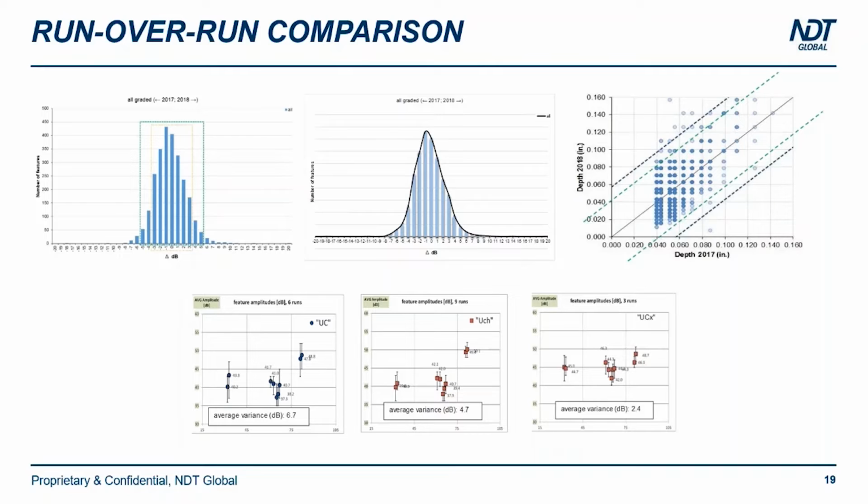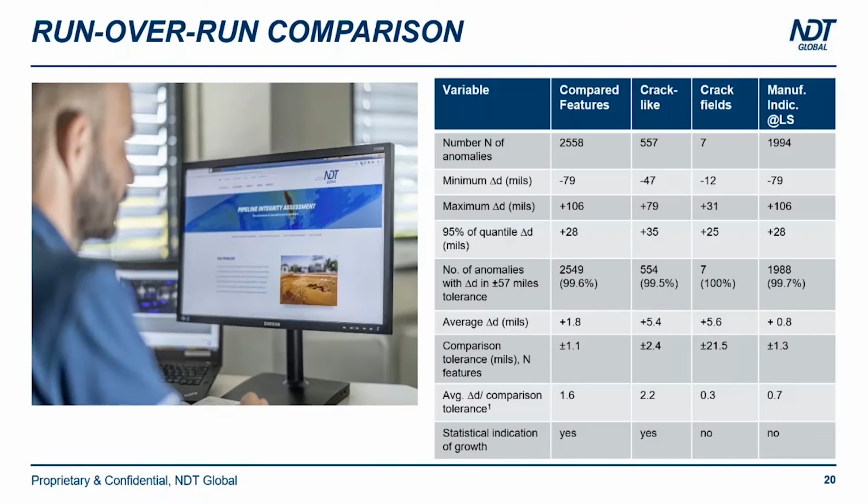So this is extremely important. This is something that is being done from the beginning for every inspection that we have. All these outliers, variances are communicated and explained to the operator beforehand, but we can also create comprehensive studies out of it. These comprehensive studies could be translated into a crack growth assessment, like the example we have on the screen.